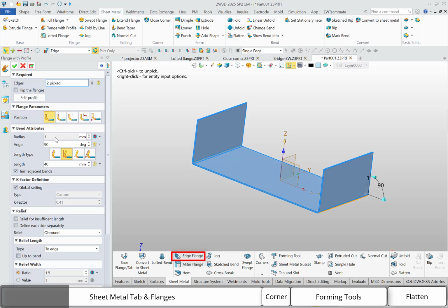And also, bend radius is one of the most important values. You may notice that the value is not allowed to change. The reason is that we have defined the global values a little while earlier. If you really need to change to a different value, just click the Dynamic Input command in the drop-down menu to unlock it. Then you are able to make the change.